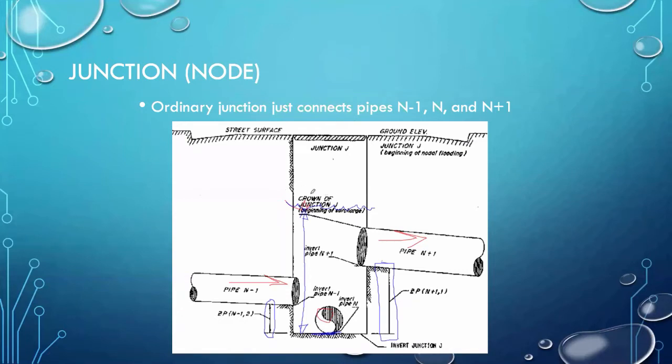So all it can compute is an elevation, and if it's required to make all the other hydraulics work that the water come up here, it will report that as the water depth, and then it's going to take this portion and declare it wasted. So it will throw that water away, and it stores it in a loss variable, and that's how we can tell if at this junction our hydraulic grade line is above the land surface.